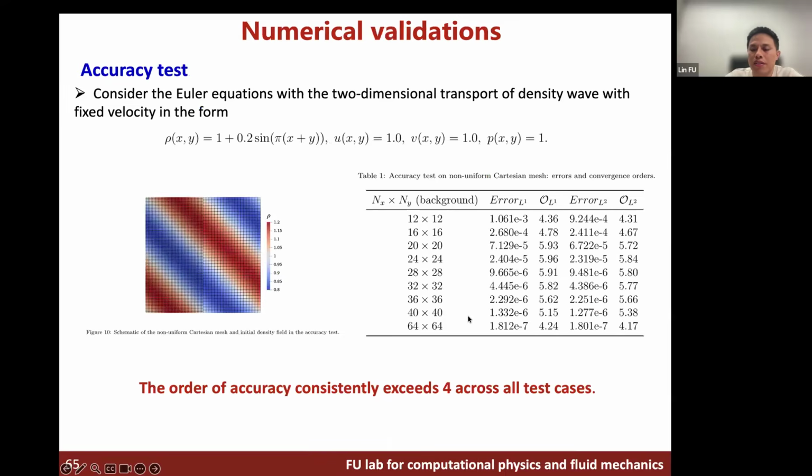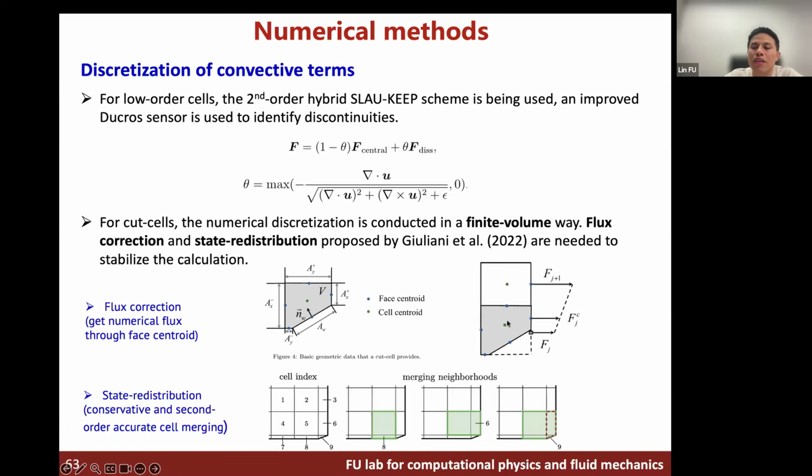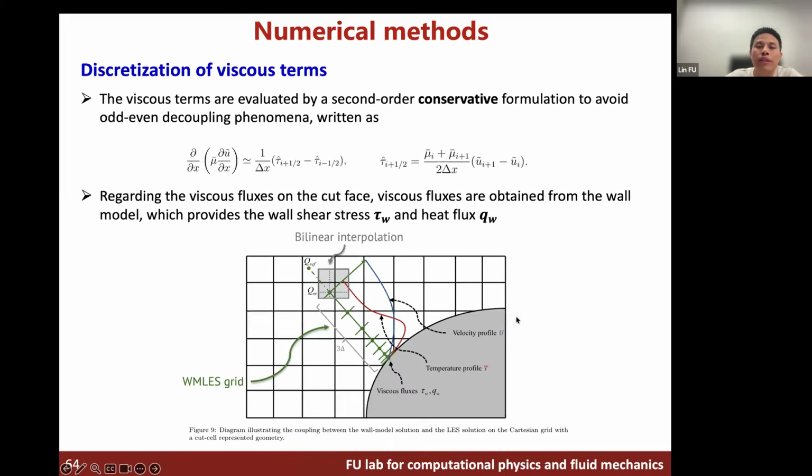Because of this cut-cell method, this near-wall turbulence cannot be resolved, so we deploy the new model, right? Inverse velocity transformation and also the VT relationship. We deploy that model to reduce the order between the wall surface and the third matching point in the near-wall regime.